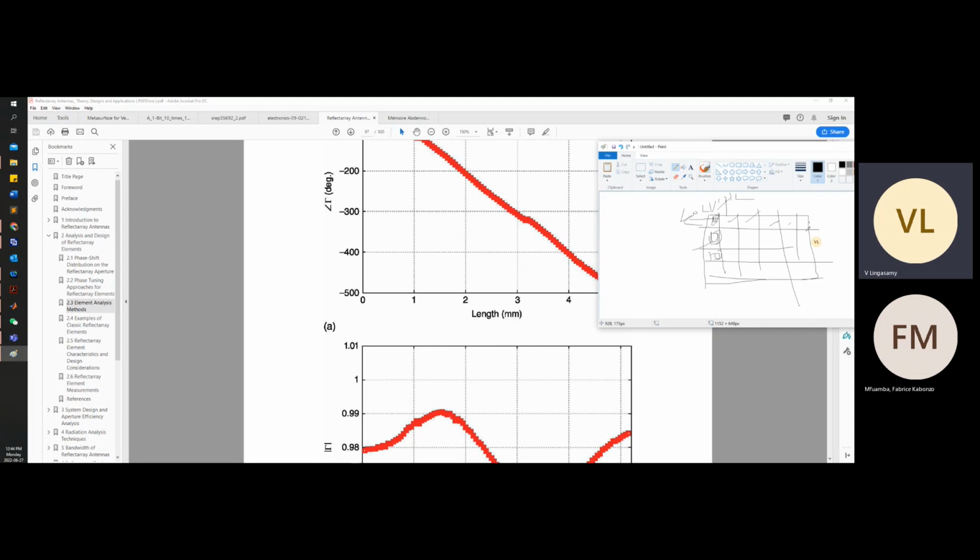You can use a feed horn, a patch antenna, a Gaussian beam, or exact plane waves, anything. How you are going to validate your array, that is the key here. You can excite with anything. Ultimately, you have to find out what response you get. If you are expecting plane waves, you will get the phase distribution in the reflected beam. That's how we are validating that your array is reflecting with this particular phase. That way you are validating with the plane wave.